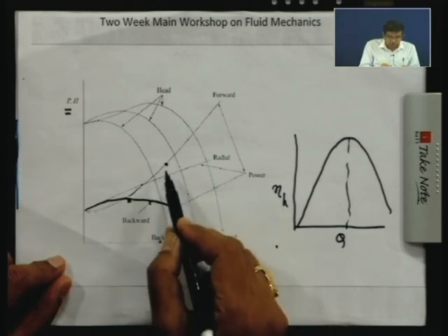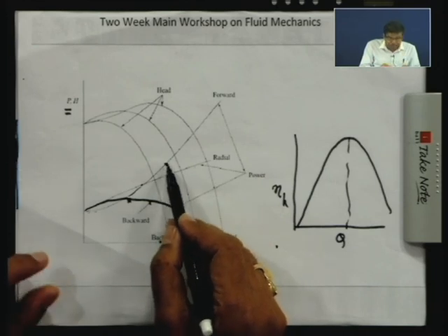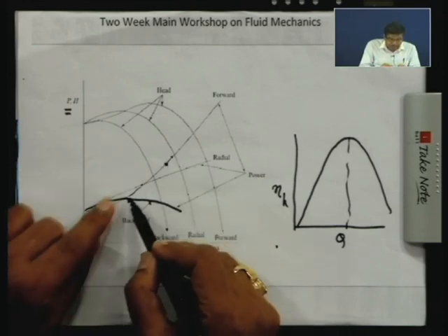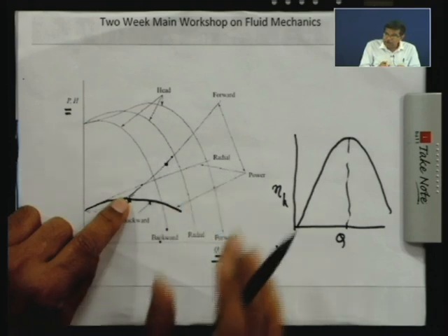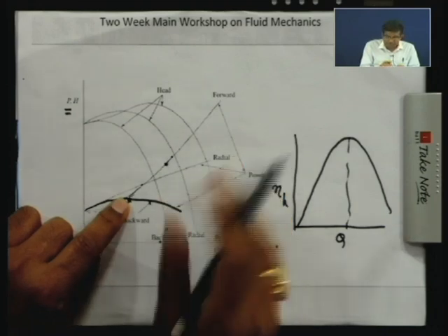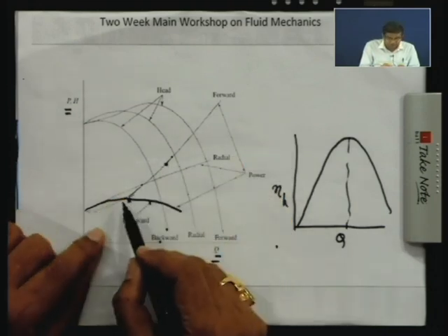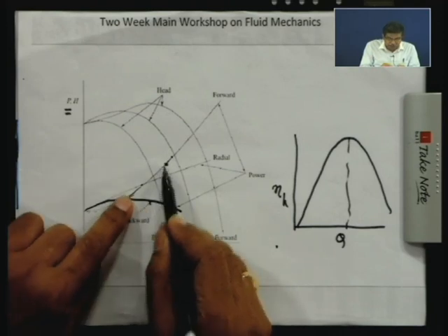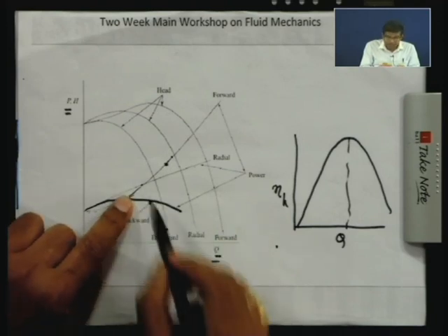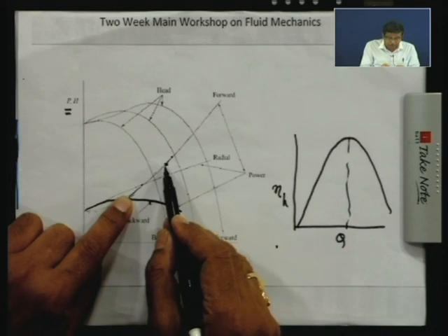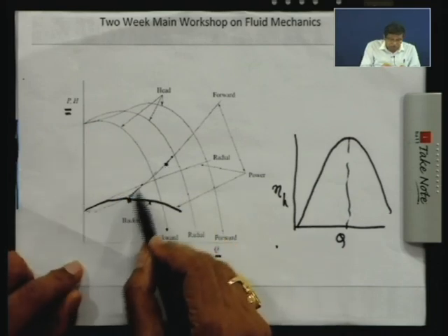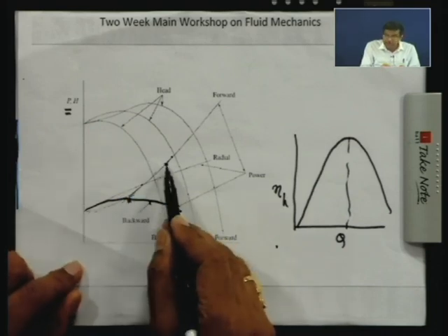You understand? So, what will happen? There will be two effects. If we rate the motor for higher power, taking a safety measure, factor of safety type, so that it can take care of the off design condition when the flow rate is increased, the power requirement. Then most of the time when it will be operating at the design condition, it will be underrated.